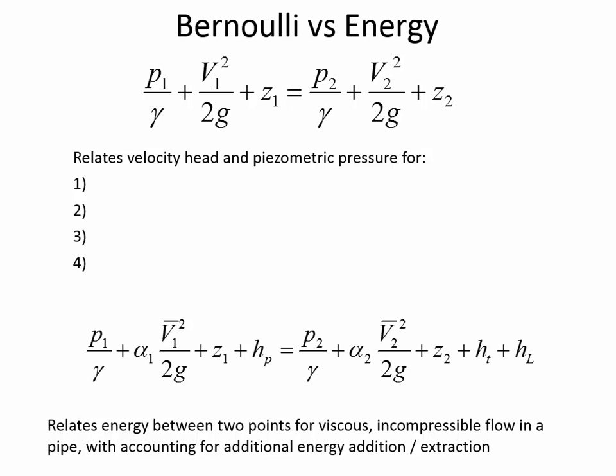And so instead of saying with Bernoulli's equation, when we said V, we meant V right here at a single location, like the instantaneous location-specific velocity. In the energy equation, we're going to say we're applying it not at a point, we're applying it at a cross-section. And so when we say V1, we mean the average velocity everywhere across that area.